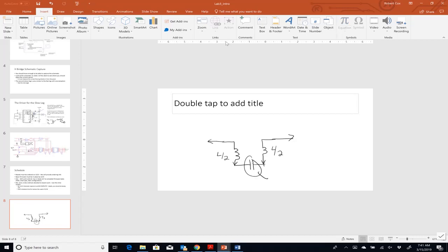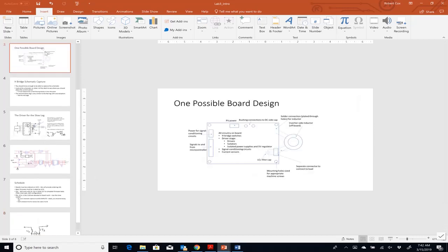The capacitor is on the board. And then you have a set of connection points to connect to a load. If I look at the LC filter, there is point 1 and point 2. Those are both connected to midpoints. Then there are these outputs from the inductor that come back to the board, and we can then connect to a load. What we told you to do is soldered connections to go to the inductor. Then we can go into another connector here to be able to connect in both the inductor and a load. Then the capacitor will be on the board itself.